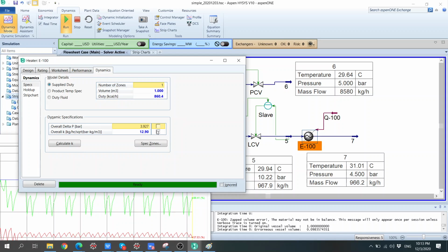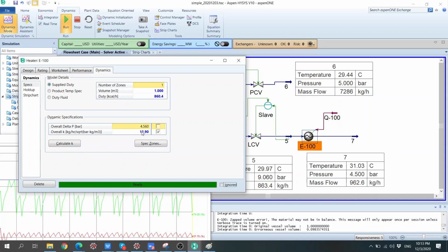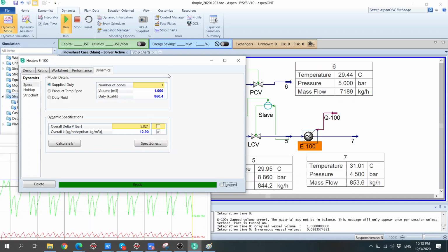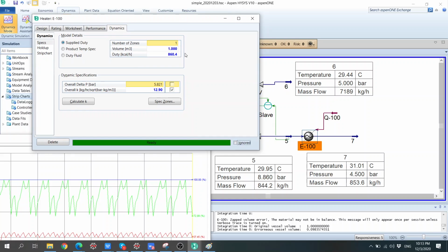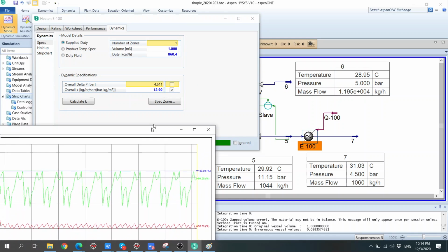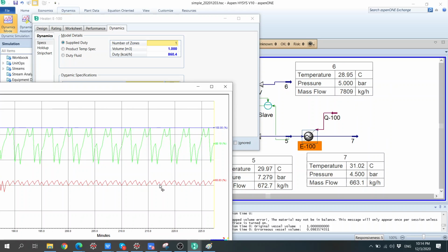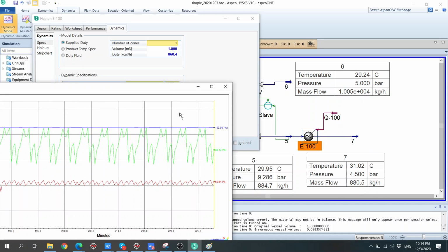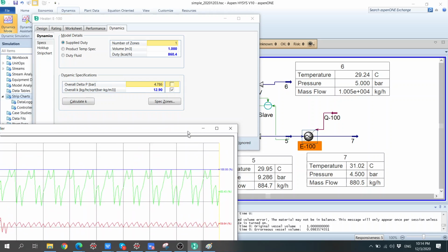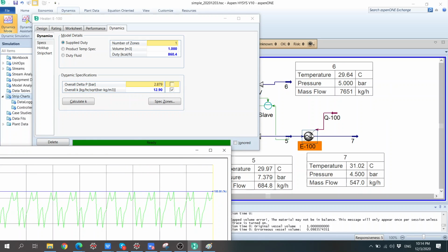And then you can see with this K, the pressure drop goes up and down very fluctuatively, so that creates the fluctuations in the system, as you can see now here. So we have reduced the Kc of the flow controller, but it's still oscillating a lot. So we can be suspicious that this could be because of the new equipment that we put in, right?